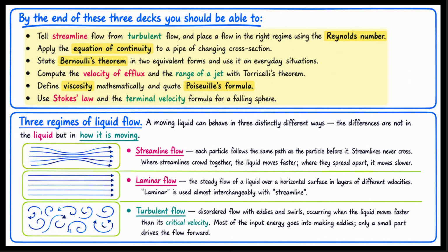You should be able to compute the velocity of efflux and the range of a jet from Torricelli's theorem. You should be able to define viscosity mathematically and quote Poiseuille's formula. And you should be able to use Stokes' law and the terminal velocity formula for a falling sphere.